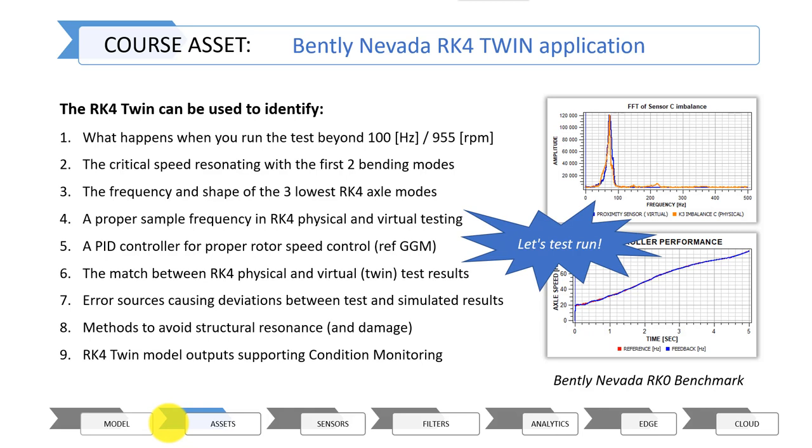And I had to verify especially the damping, and I had to verify the physical stiffness in my test rig, especially in the bearings, due to the different eigenfrequencies in the horizontal and vertical plane. So I identified that there were some issues on the physical test rig.